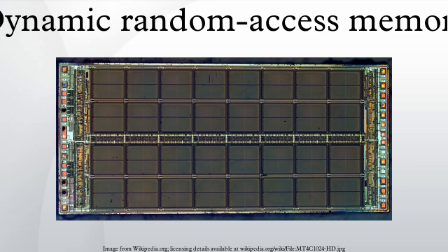It is the RAM in desktops, laptops and workstation computers, as well as some of the RAM of video game consoles. The advantage of DRAM is its structural simplicity. Only one transistor and a capacitor are required per bit, compared to 4 or 6 transistors in SRAM. This allows DRAM to reach very high densities.